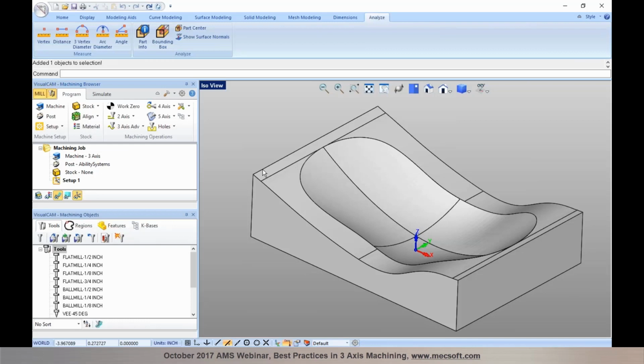As far as the STEP file format goes, we have AP203 and AP214 file formats, and you could use either one when you translate files into Visual CAD/CAM. Both file formats should work, and you should be able to translate your files fairly well. If you notice any translation errors or issues, you may want to try one of the other formats, as it could be specific to the geometry. You could use IGES or one of the STEP formats. So I'm going to turn this back to Krish.